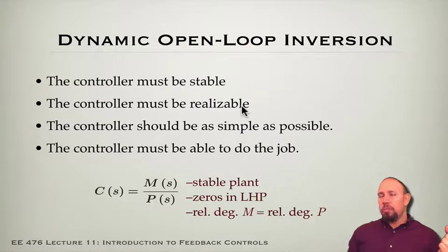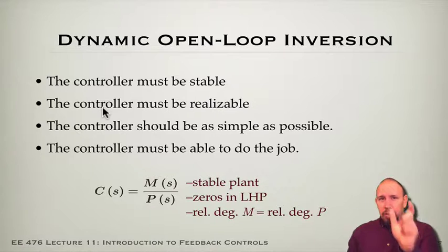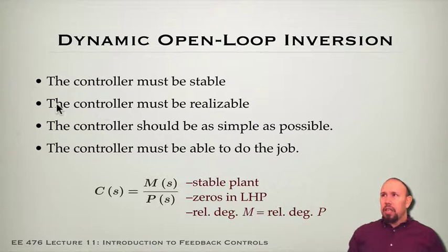The controller must be realizable. That is, it has to be causal. In terms of transfer functions, a transfer function in the Laplace domain is causal if the order of the numerator is less than or equal to the order of the denominator. So in designing a controller, the controller must be realizable.